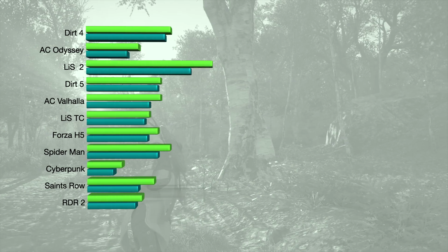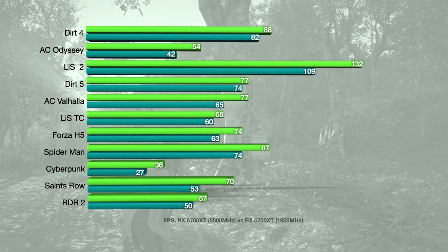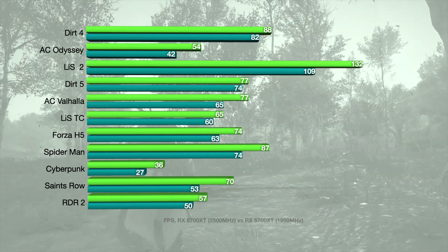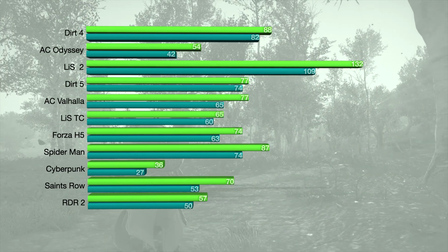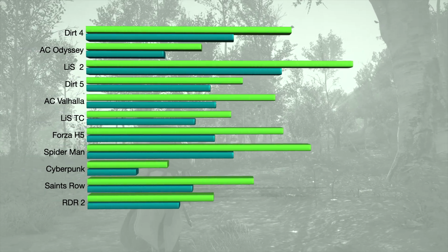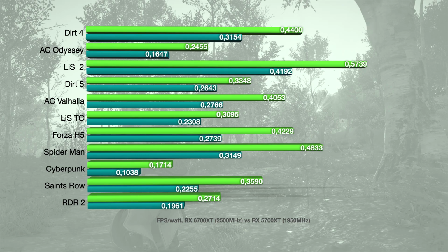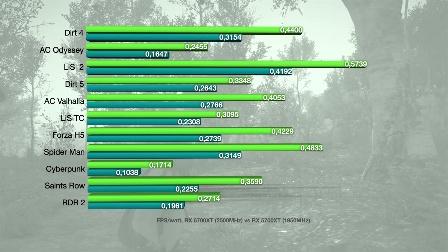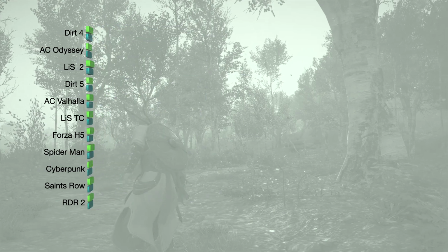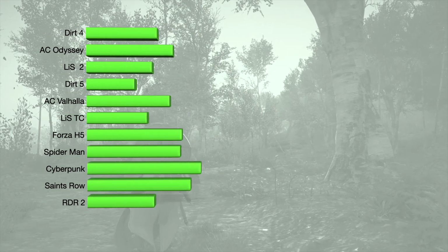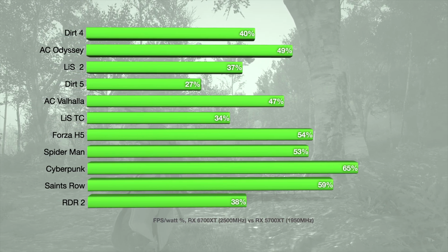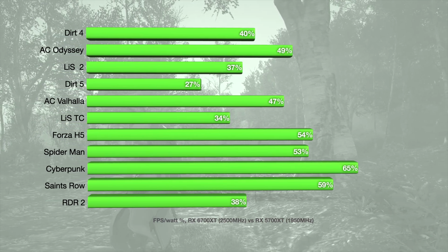However, when the high frequency and RDNA 2 IPC advantage combine, the magic happens and 6700 XT becomes a much stronger card than RX 5700 XT. Moreover, I would also like to touch slightly on power efficiency and consumption here. Based on our main testing stocks, RX 6700 XT shows a massive FPS per watt improvement that can reach even 65%. This number can vary from one game to another massively, so there is no such thing as a constant improvement.